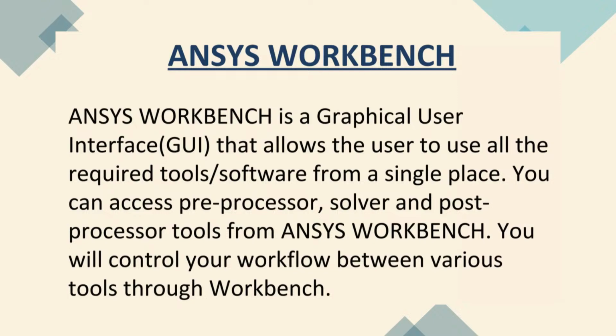And after that, if you want to do the post processing using CFD Post, then click CFD Post, and it can take all the results from the Fluent you already calculated. So, it is a fantastic way of working using Workbench. You do not need to handle all these components separately, because geometry is separate, meshing is separate, then you set up and then you run, all are actually separate files. But the Ansys Workbench is connecting everything together. So, it is a very nice tool.